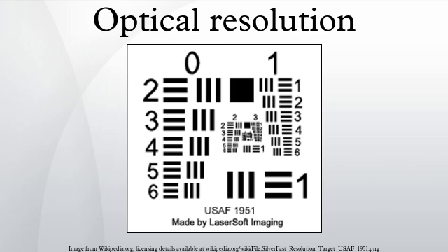CCD and CMOS are the modern preferences for video sensors. CCD is speed limited by the rate at which the charge can be moved from one site to another. CMOS has the advantage of having individually addressable cells, and this has led to its advantage in the high-speed photography industry. Vidicons, plumbicons, and image intensifiers have specific applications.